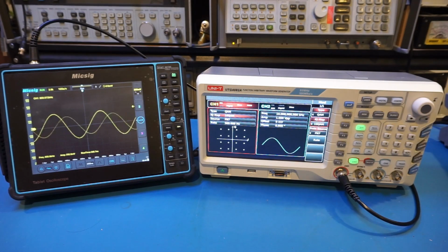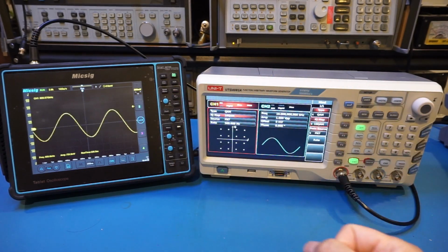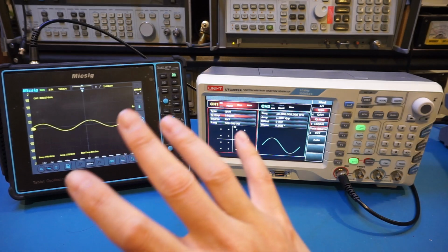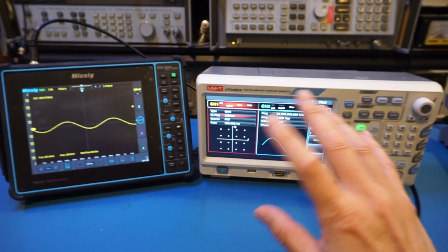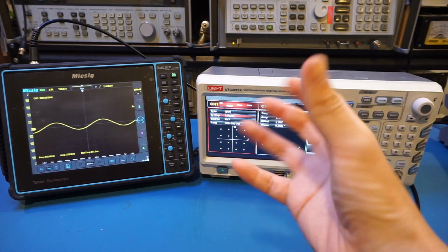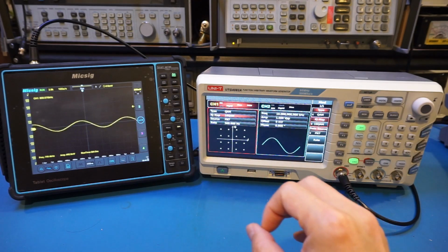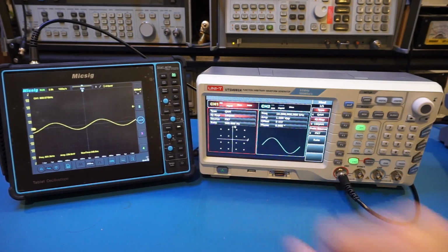A commonly used technique for observing this type of signals is to use an eye diagram. Now, we should be able to produce an eye diagram. The majority of low-end scopes typically have issues producing an eye diagram because most lack the clock recovery capability. But here we have these repetitive signals, so we should be able to get something on the mixsig.